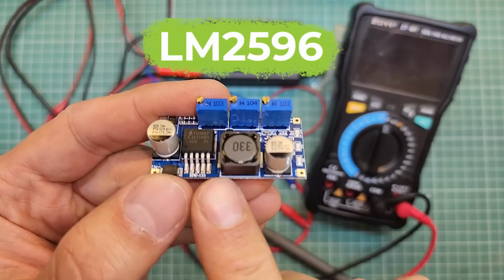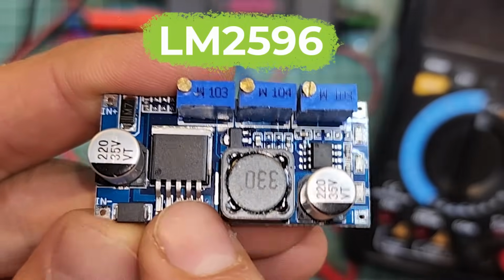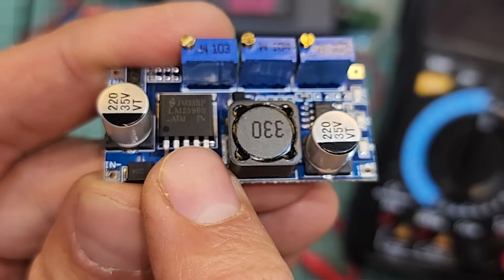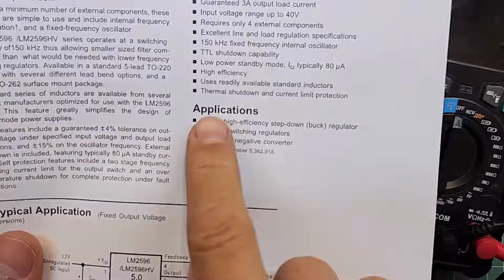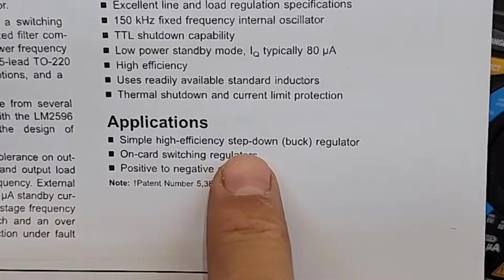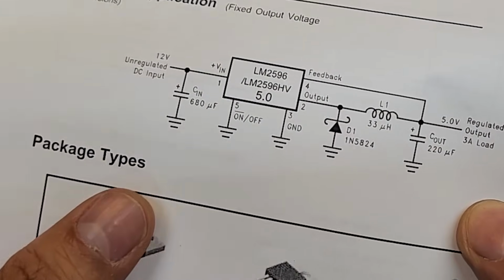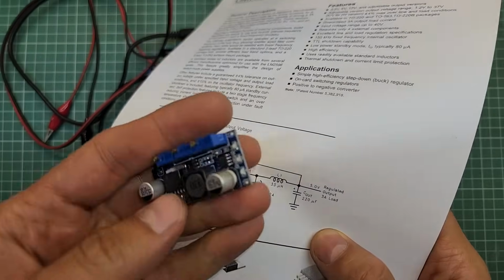This is an LM2596 switching regulator module. The IC itself is here. Look, this is the LM2596 IC, which is a switching buck regulator. Look at its datasheet. It's here. Simple high efficiency step down buck regulator, and this is the simplest circuit to make this IC up and running.